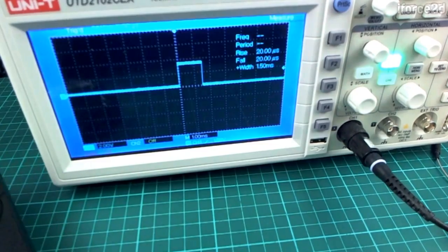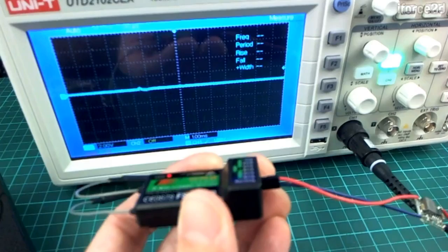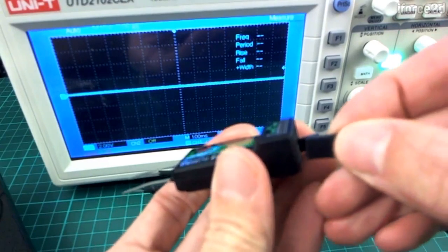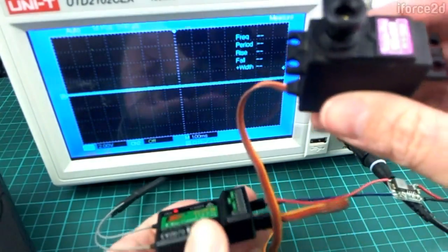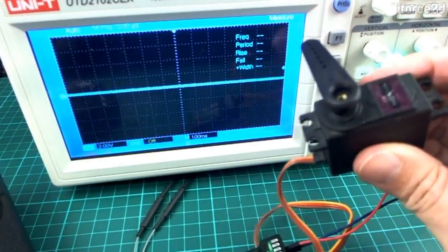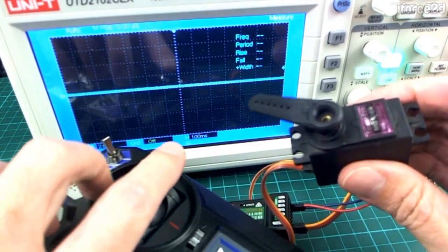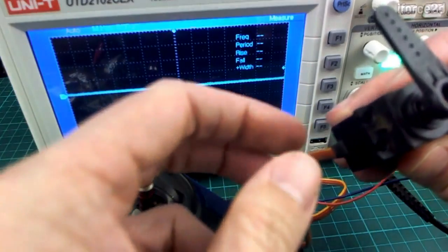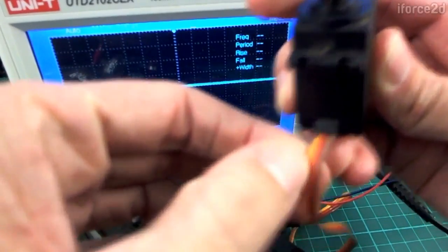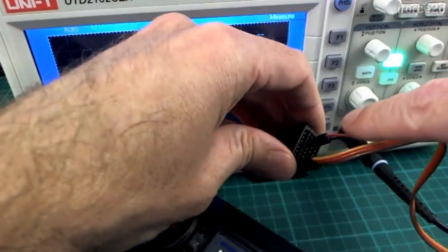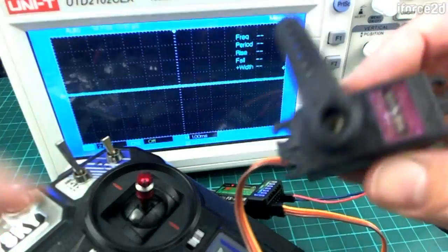And it turns out that if I just disconnect this plug and plug in a servo to the same place, now my servo is running off that connection, and I can control my servo in the same way. And the servo of course requires power to run, so what's happening here is that the middle wire is taking its power from that middle rail where all those pins are connected in the middle. So that's how it can power itself.